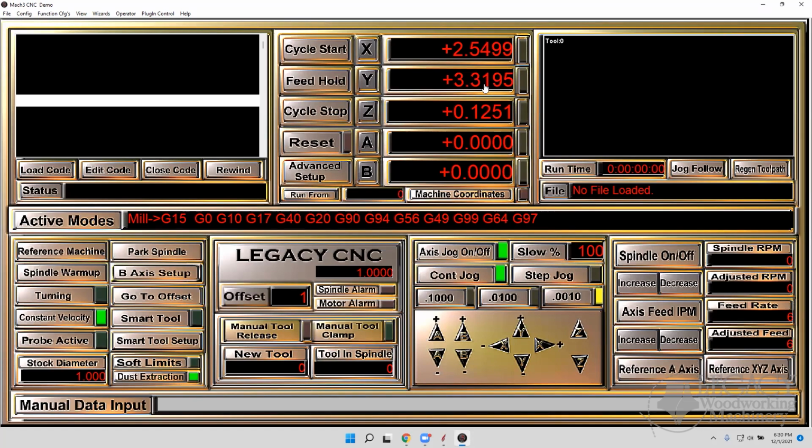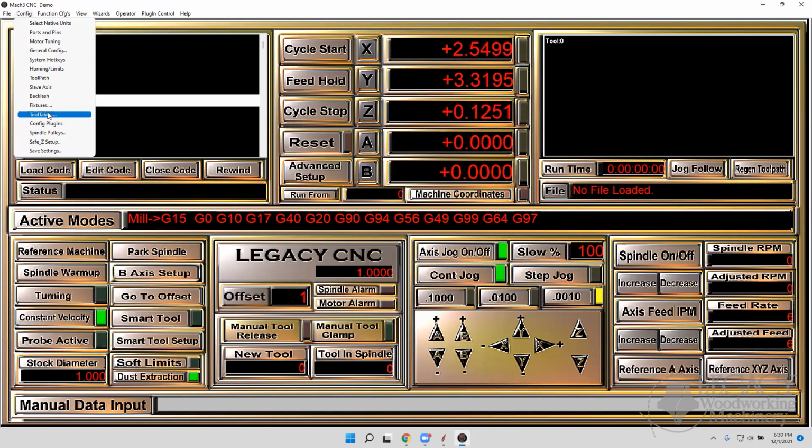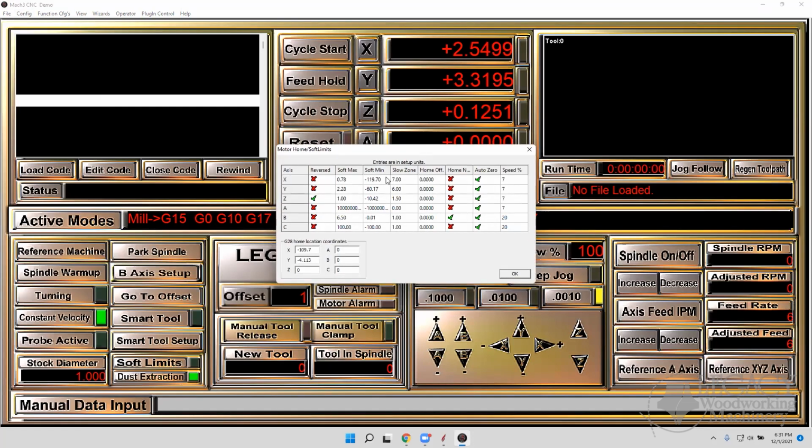Okay, you're going to go to Control and go to homing/limits. Limits is the key, right? If we were doing the Y and it was the minimum, you would change that number right there. If it was the maximum to the left side, it would go here. And on the X, your max would go here. My numbers here, pay no attention to my numbers. I just put the software in. I haven't set this up. These are arbitrary, random, stupid numbers.